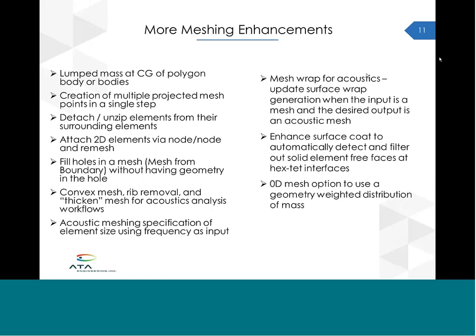There's another great enhancement to detach and unzip elements from surrounding elements, and I'll show you an example of that in a subsequent slide. Along with detaching or unzipping elements, the counterpart to that is attaching elements through a local remeshing process. You can fill holes in a mesh without having geometry to explicitly define the hole.